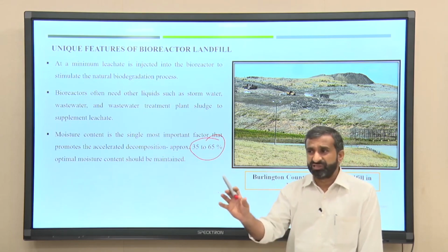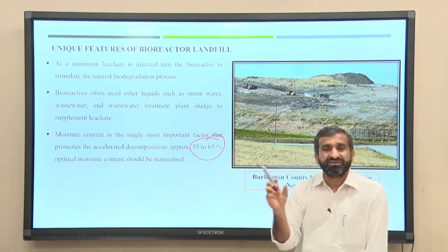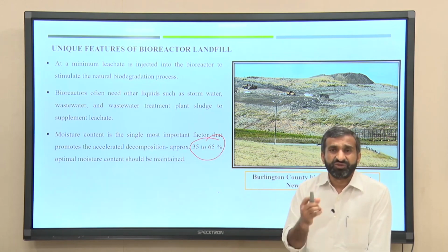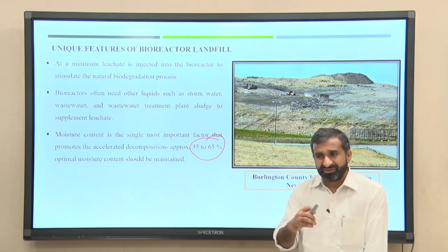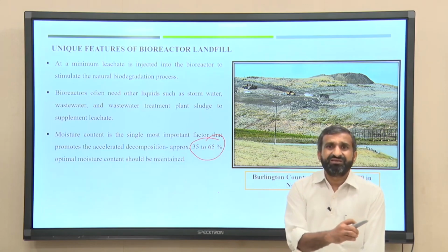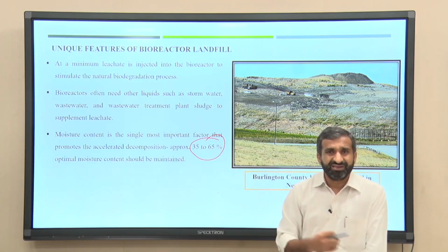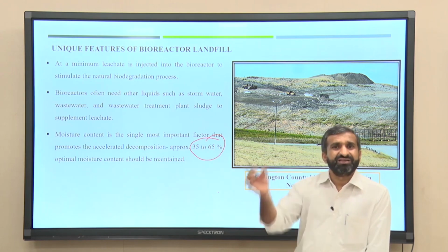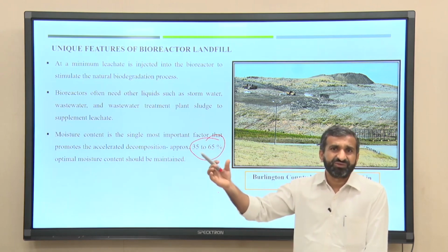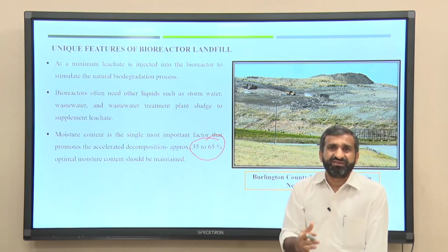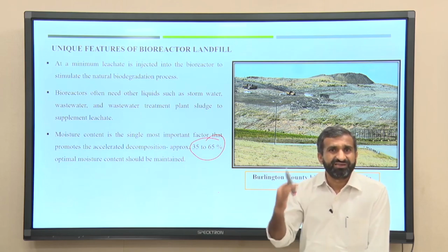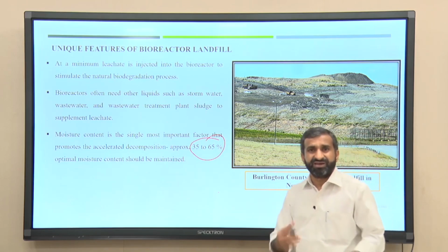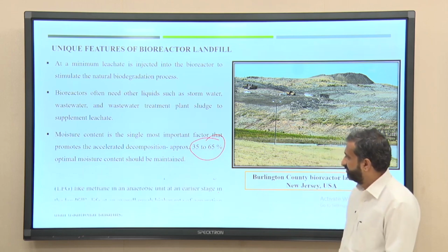How will degradation be fast in that time? The simple thought is that the leachate you collected in the 3 months of the rainy season, you collect it and supply it again over the remaining 7 to 8 months to wet the entire mass, because once it gets wet, the degradation will be very fast in the waste material.